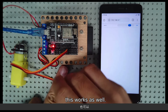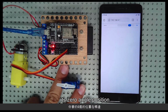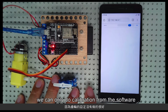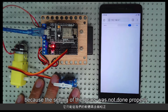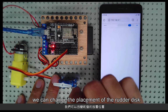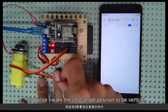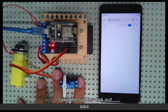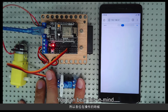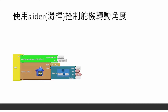This works as well. You just need to take out the rudder disc, reattach it, and you can decide its 0 angle position. Of course, sometimes we can only do calibration from the software because the setting of the gears was not done properly. However, from the appearance perspective, we can change the placement of the rudder disc to change the 0 angle position. Suppose I want the 0 angle position to be vertical, take the rudder disc out and place it this way for the 0 angle. You can bear this in mind when operating it. We'll let you operate on it yourselves.